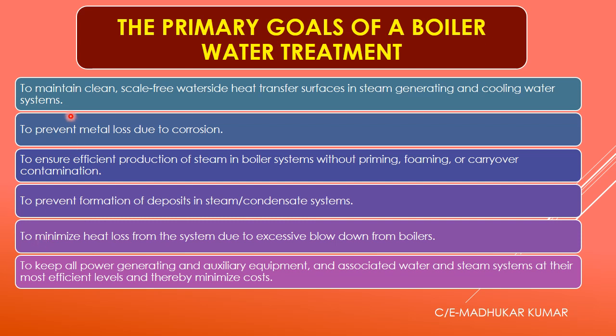This is to maintain a clean, scale free water side, that is basically your heat transfer surfaces in the steam generating and cooling water system. So why is it necessary? Because otherwise it is going to impair the heat transfer, and finally it is going to increase the fuel consumption required for the generation of steam. So if you have a clean and scale free surface for heat transfer, it is going to raise the steam in less time and with less heat required.